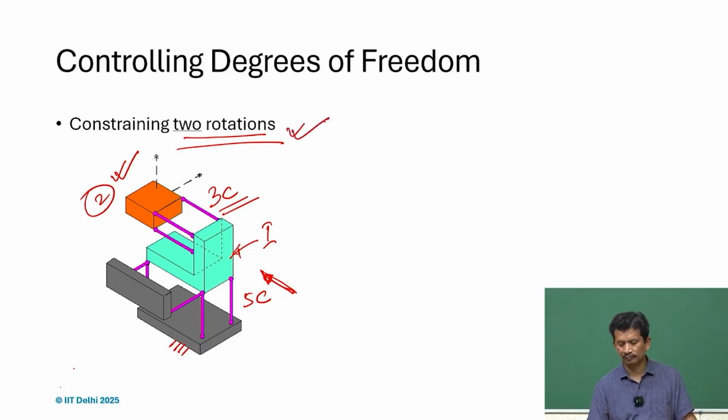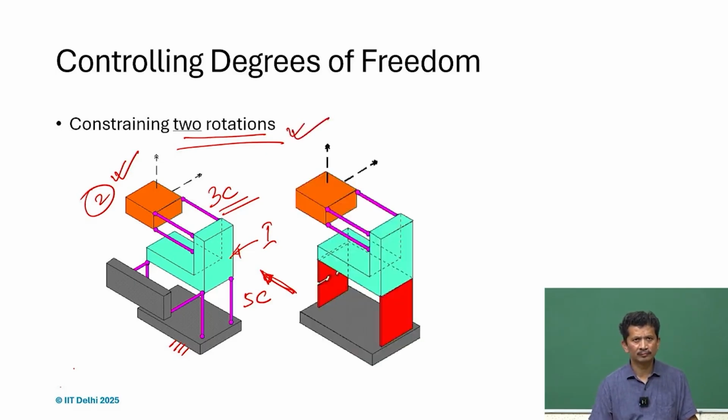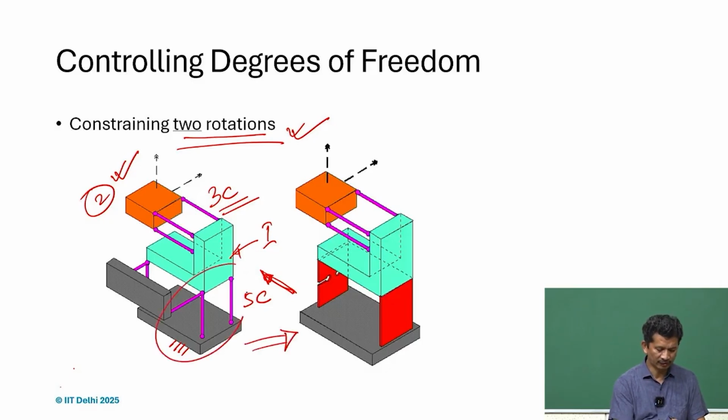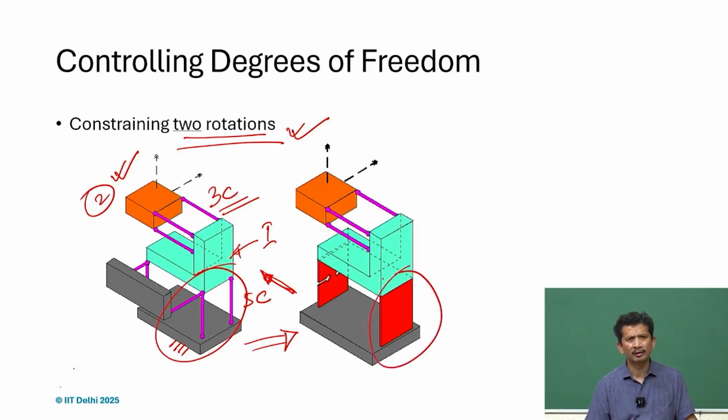And we can always try to find an equivalent design. So, these three constraints in a plane, we can always replace with the sheet flexures, and these two in a plane. So, we can always put another one with the hole, and that provides two constraints.